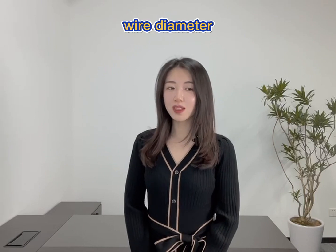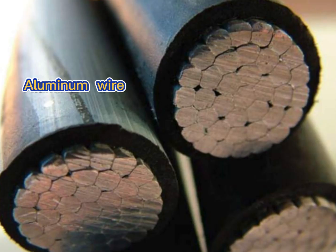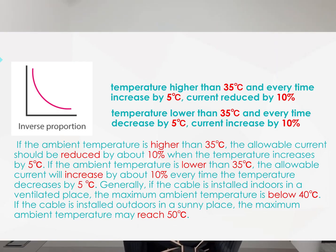Cable current carrying capacity is determined by the material, wire diameter, and temperature. Cable can be divided into two kinds, copper wire and aluminum wire. Each has its advantages. If the ambient temperature is higher than 35 degrees, the allowable current should be reduced by about 10% when the temperature increases by 5 degrees. If the ambient temperature is lower than 35 degrees, the allowable current will increase by about 10% every time the temperature decreases by 5 degrees. Generally, if the cable is installed indoors in a ventilated place, the maximum ambient temperature is below 40 degrees.